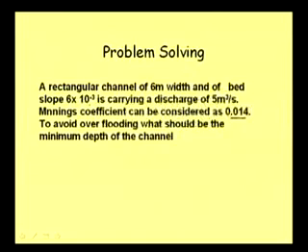0.014. As we know, Manning's coefficient we always give some value, depending on whether the channel is man-made or natural. In a field situation, based on some characteristics we can say that the Manning's roughness value should be this much, but in the entire channel reach you may find differences.